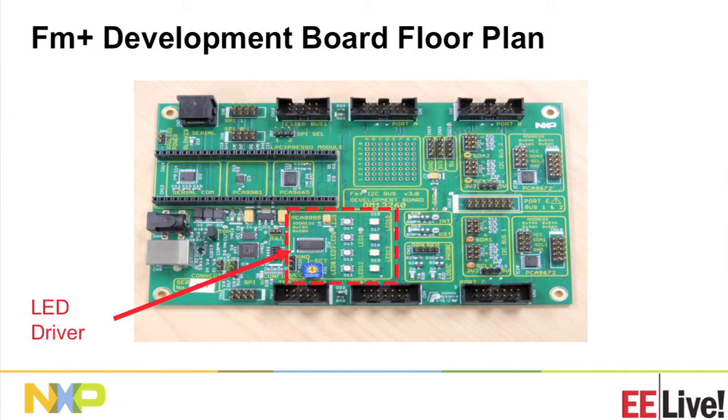When you use that chip, you have to decide what the maximum current will be through your LEDs. That's a hardware consideration. So on our demo board, we use the rheostat or potentiometer, so you can adjust it. You can run 20 milliamps through the LEDs all day long, you won't damage them. But the part itself will provide up to 57 milliamps per channel of drive current. So move that screwdriver with caution.